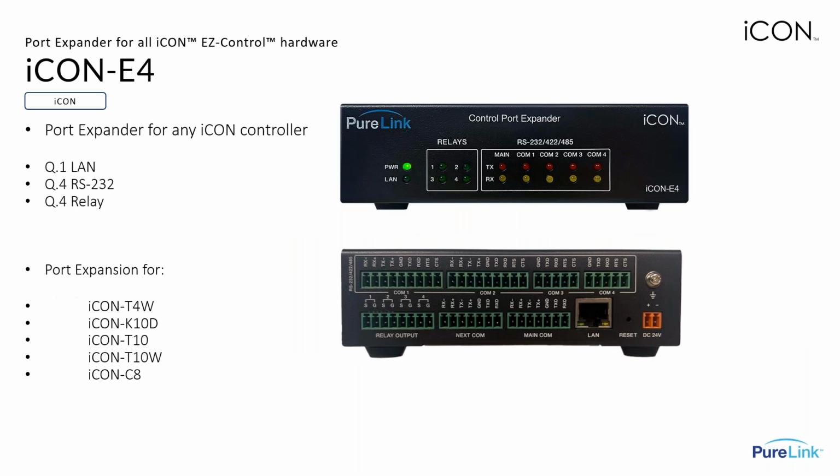And this is the iCON E4. So this is the port expander for any iCON controller. It includes one LAN port, 4 RS-232 ports, and 4 relay ports. And this allows the expansion of any of the previously mentioned controllers, and we'll get into the actual specifics of how it's read through the software, but it can just be, as mentioned, a relay to communicate to more devices if the project you're running is too big for the C8 and its available ports, or if you just want some additional COM ports to be controlled all through your T10 or T4W or something that only has one RS-485 port.